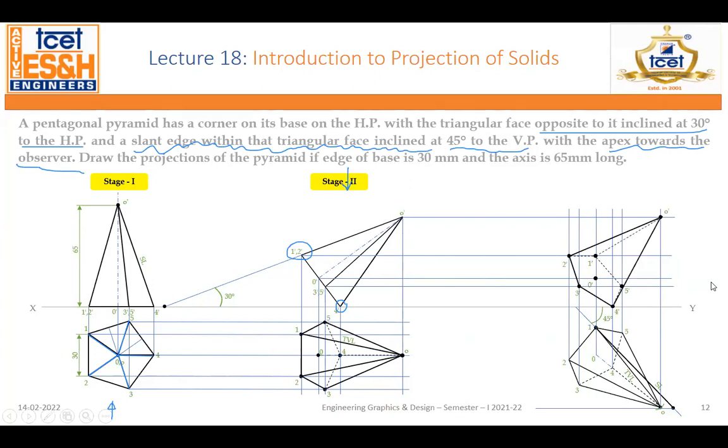Now here you have to be very careful that you check the outer points, all the outer points, first you have to make them dark. Same procedure, what I have told you. Outer points you have to make dark. After that, what you have to do, just have a look. यहाँ से देखो. When you see from here, farthest point कौन सा है? तो farthest point आपका 1 है. तो 1 से associated whichever line will be, सब hidden हो जाएगा. See, this is hidden, this is hidden, and this is also hidden.